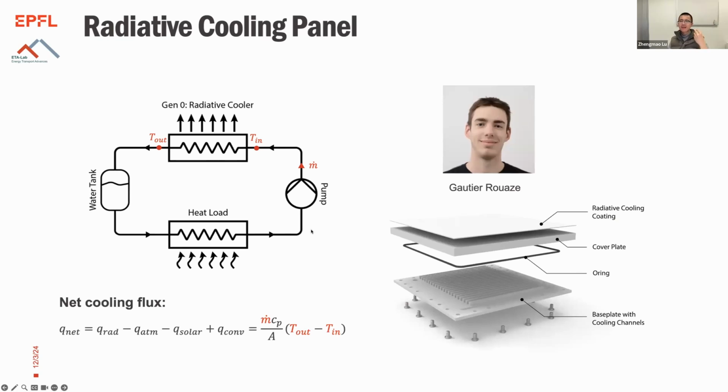Basically, we're trying to create our own long-term outdoor radiative cooling platform. By measuring the flow rate and the temperature difference between inlet and outlet with a radiative heat exchanger, we can characterize the radiative cooling power in a more realistic sense.